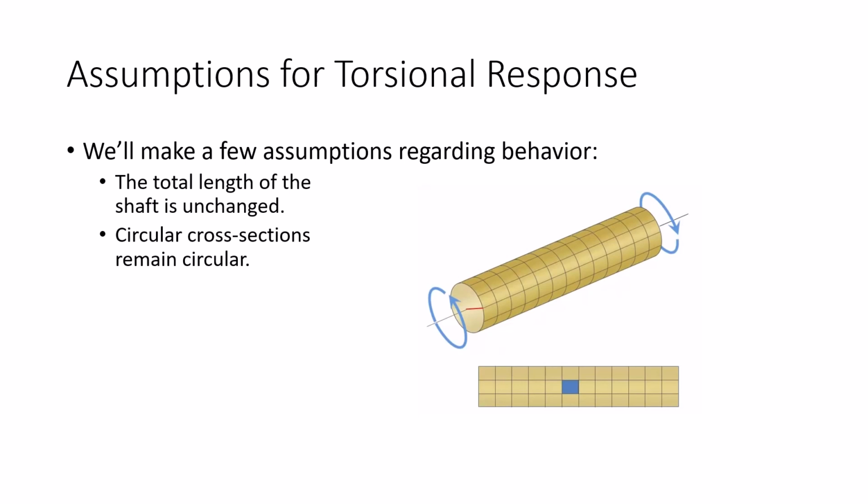What I am interested in is your attention, because we're going to arrive at a certain cross-sectional property, and that cross-sectional property is new, okay? For example, when we did axial stress, we found that the stress was computed by taking the applied load over the cross-sectional area, right? And that area was a number. The cross-sectional area is 4 square inches or 6 square inches, and that number is a characteristic that defines what that shape looks like, right?